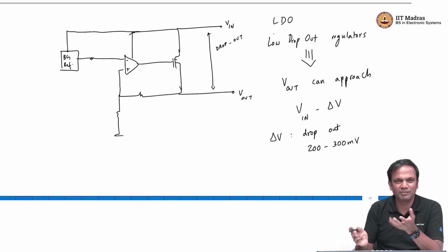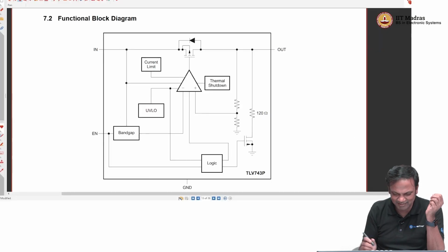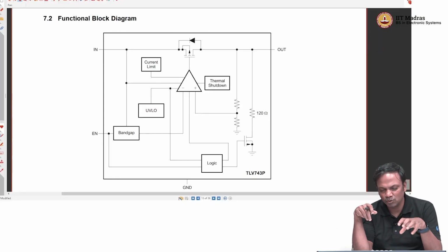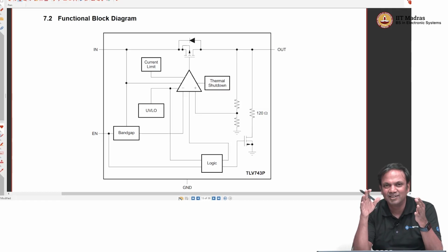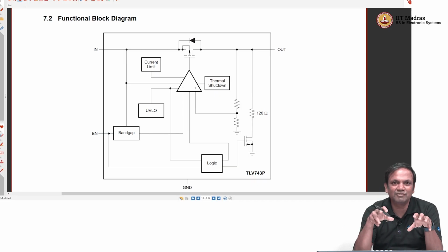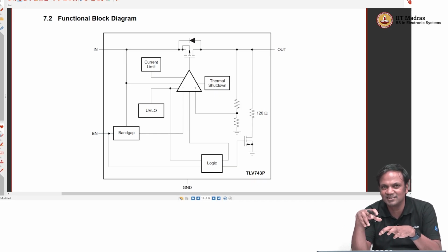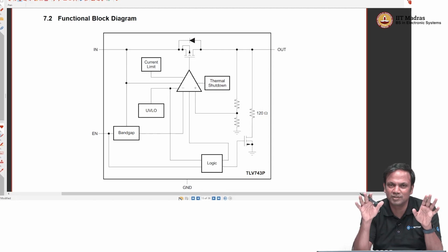It is not very different, maybe rotated by 90 degrees, but otherwise the same, right. So, there is the feedback circuit, and I think I understand the fixed voltage better now. So, what they say is they have different parts for different fixed voltages. So, maybe the LDO is the same, they will just change these resistors depending on the output voltage you want.